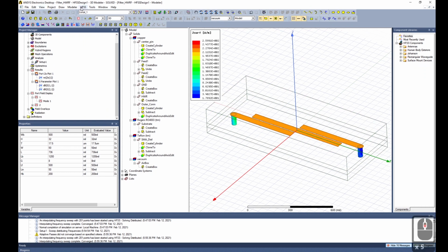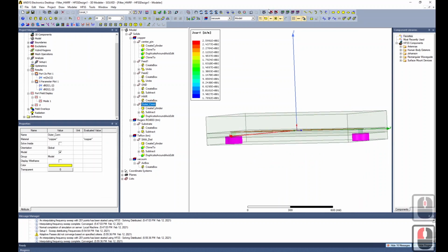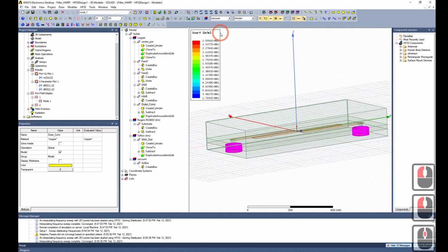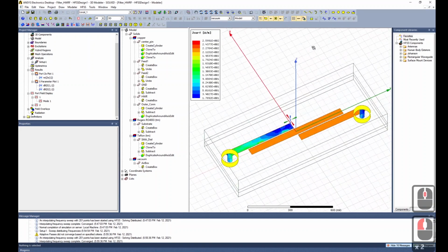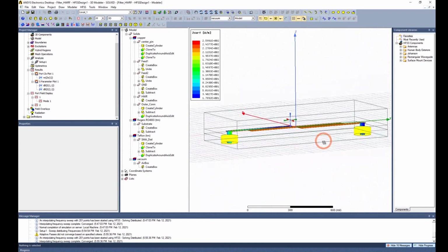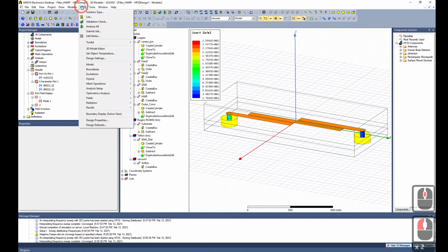So you would go to, well actually first let's go ahead and add back in the connector in the viewport just for kicks. So add this connector back in here. Okay, cool. So suppose you wanted to put a 0 degree phase on this element and a 30 degree phase on port 2. So you would go to HFSS,